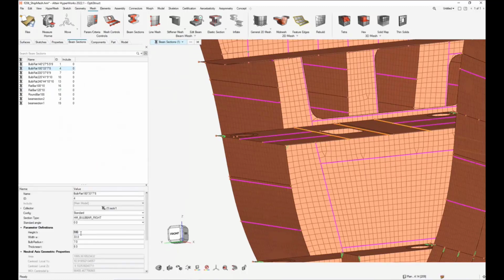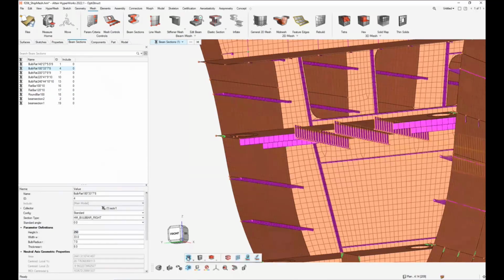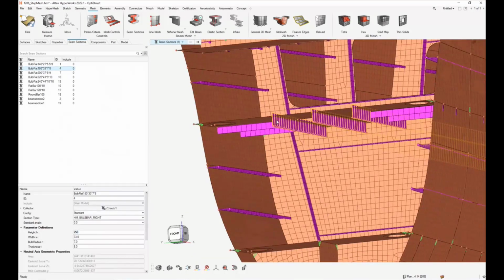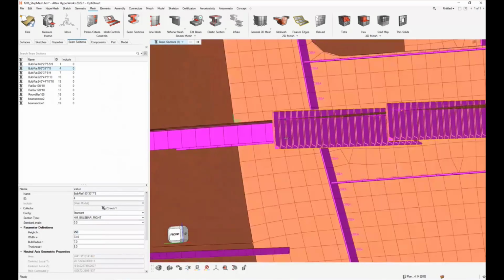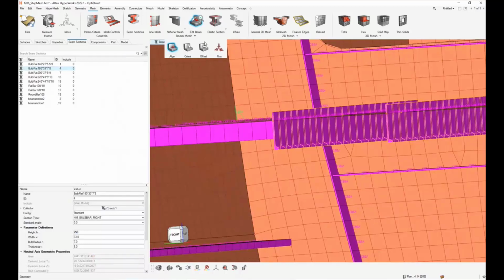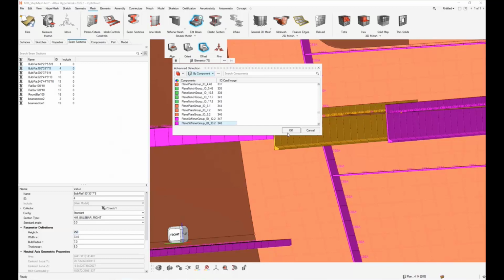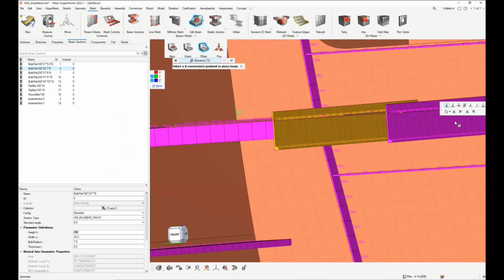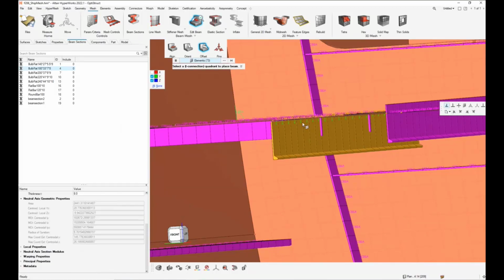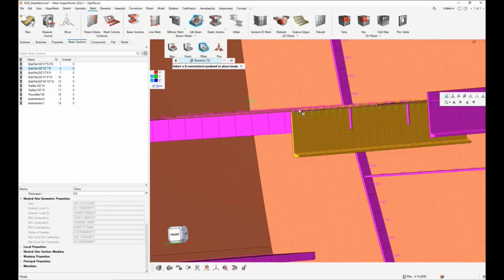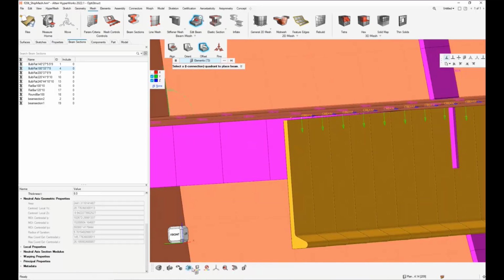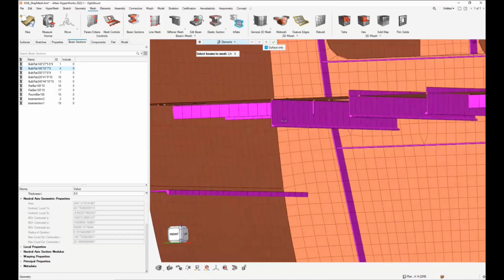Select the beam section and let me change it. Turn on 3D. Since I changed the size, the offset is not correct anymore. So I can go to offset and reselect those components and let me replace it properly, accounting for the shell thickness. Yeah, switching shell thickness. And the main point is that now we can inflate it.